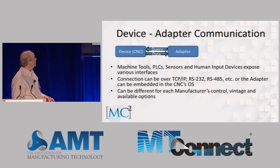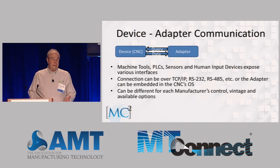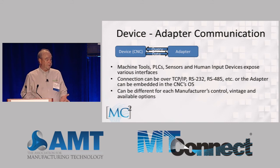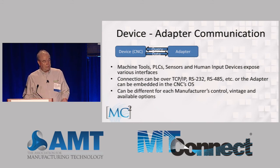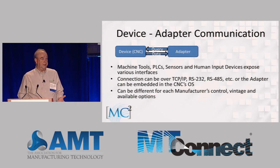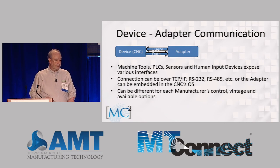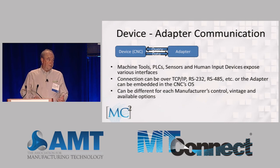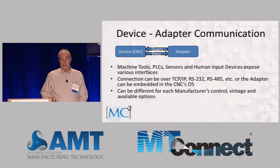Okay, so let's talk a little bit about the device adapter communication. So the machine tools, PLC sensors, human input devices expose various types of interfaces. They typically can be connected either TCP/IP, RS-232, RS-485, etc. Or the adapter could actually be embedded into the operating system, in which some cases they actually do that. They actually pick up the data directly from memory within the operating system. They can also vary quite significantly between manufacturers, control, the vintage of the control, and potentially available options that are on that control.